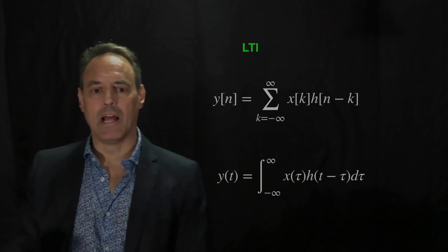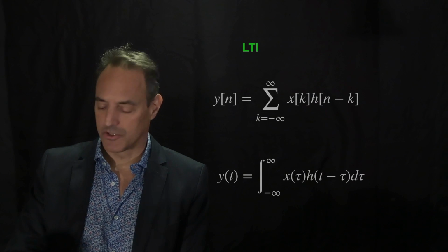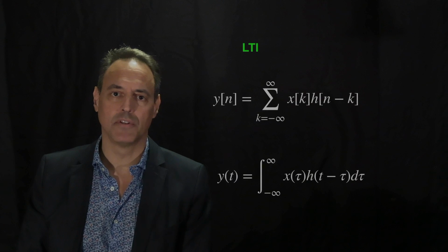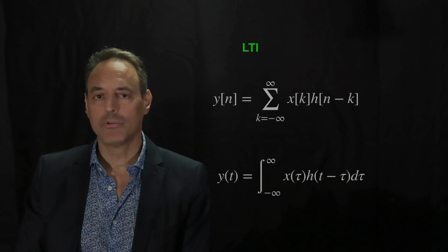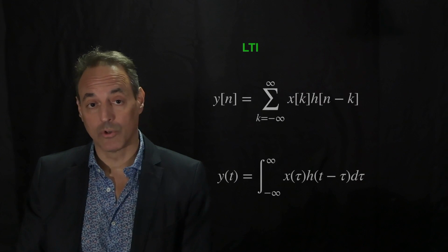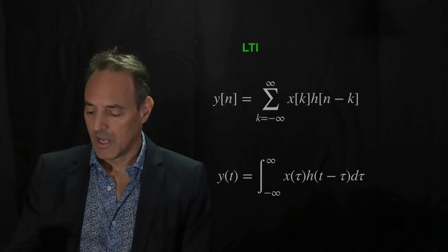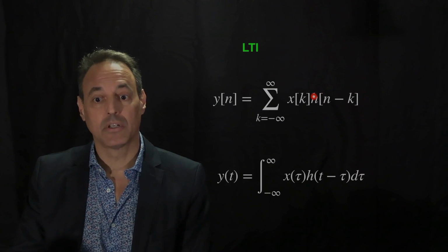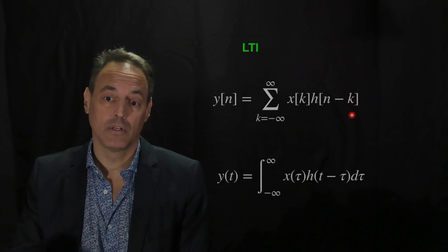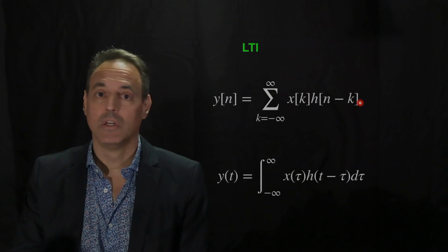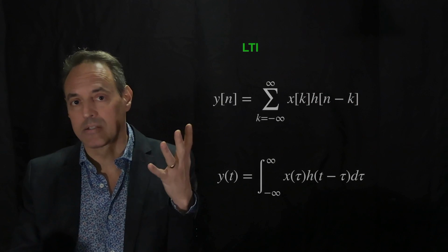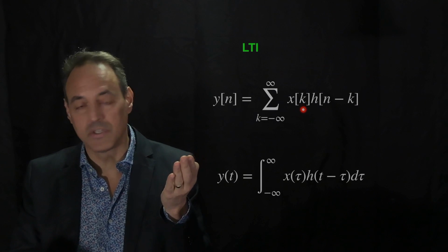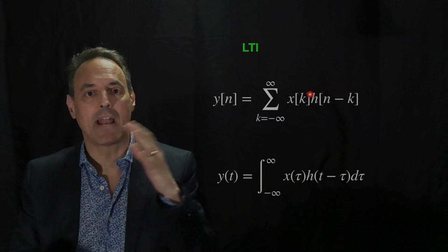Again, for LTI systems, discrete or continuous, we have these very simple representations of the dynamics. We're making use of the sums, or the integrals, which are the limit of the sum. We're just saying, put in an initial signal and ask what the kick does. Well, it's dictated by h. A signal is just a series of kicks, as it were. If I know how it behaves to one kick, I can say a signal is a bunch of kicks, and I just add them all up.